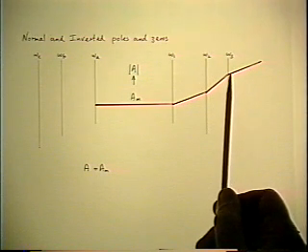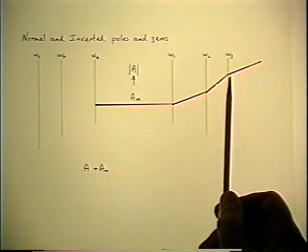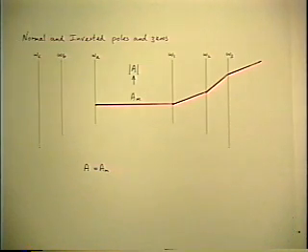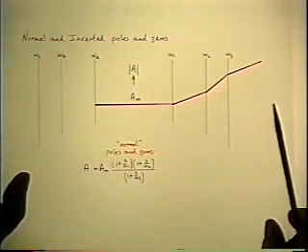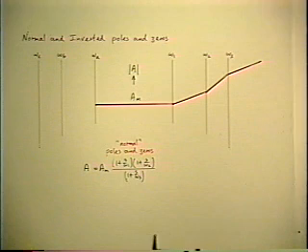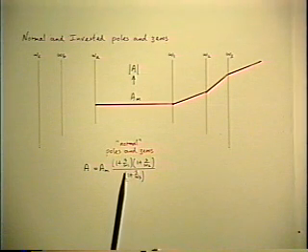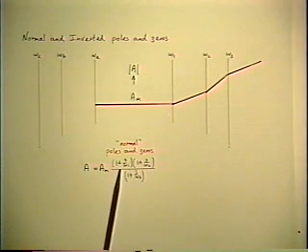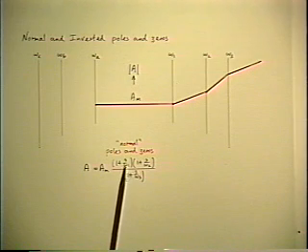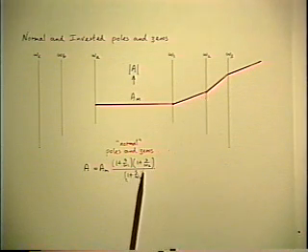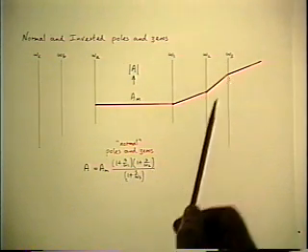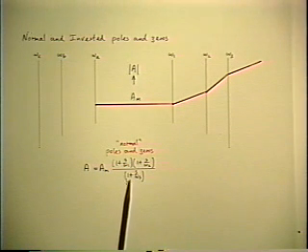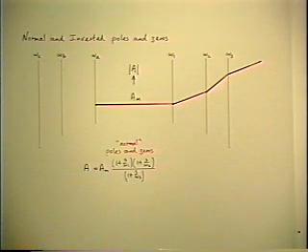So that's a concave downwards corner. That's a pole. So the factored pole zero expression that goes with that sketch looks like this. The omega 1 is a zero, so it's a 1 plus s term in the numerator. The omega 2 is the same. The omega 3 is a pole. The 1 plus s term is in the denominator.